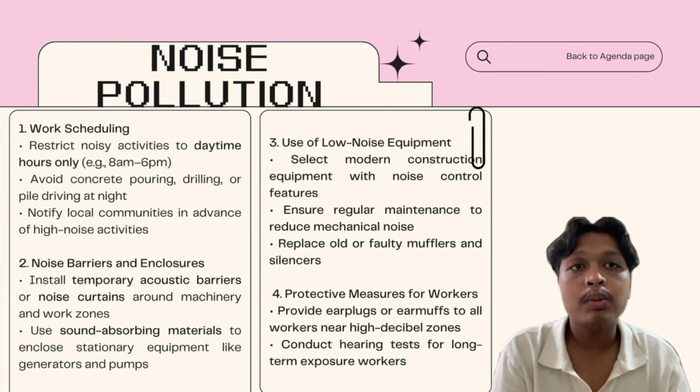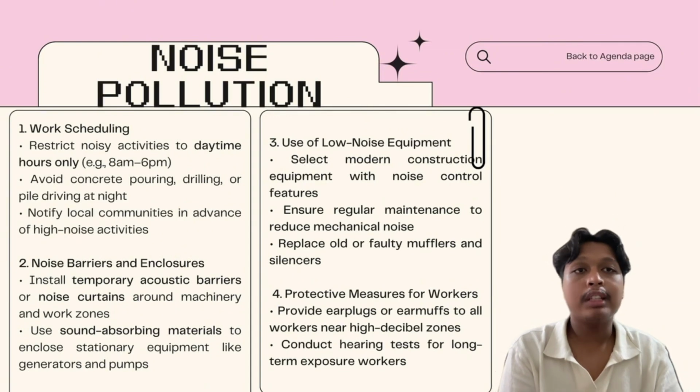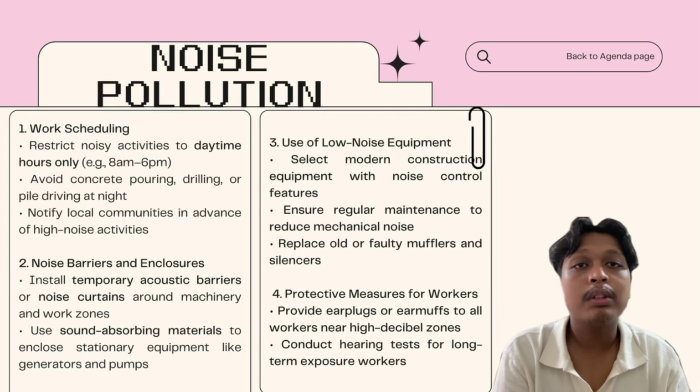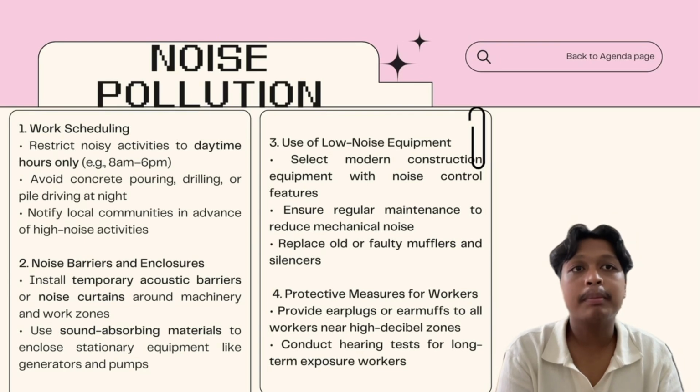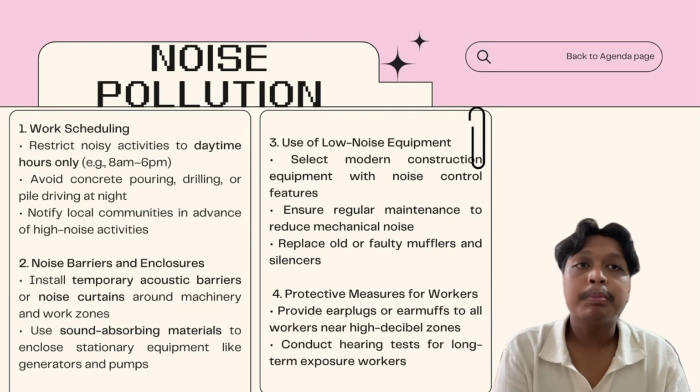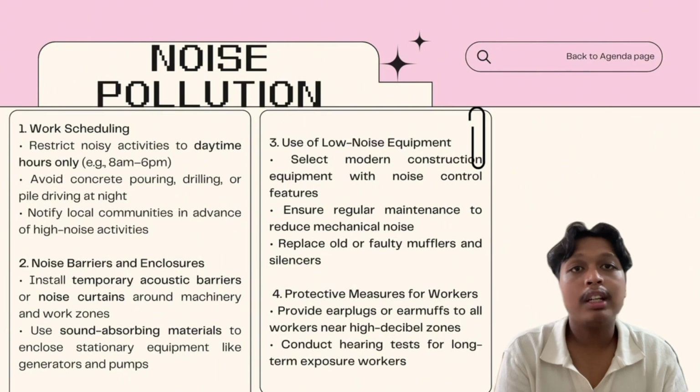Finally, to protect workers, we must provide ear protection gear such as earplugs or earmuffs, especially for those working near high noise areas. Routine hearing checks should also be conducted for long-term workers. By applying these measures, we can reduce noise pollution, protect public health, and maintain a safer and more comfortable working environment.